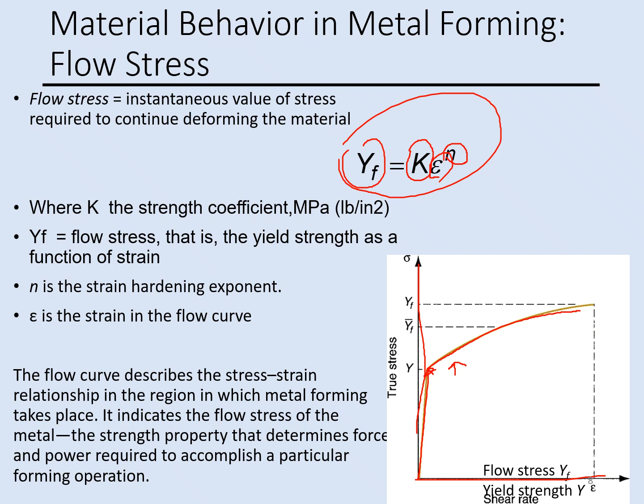The main cause is called strain hardening, and that is a process of making a metal harder and stronger through plastic deformation. When a metal is plastically deformed, we have dislocations in the metal that are going to move, and these dislocations are generated and become more and more.